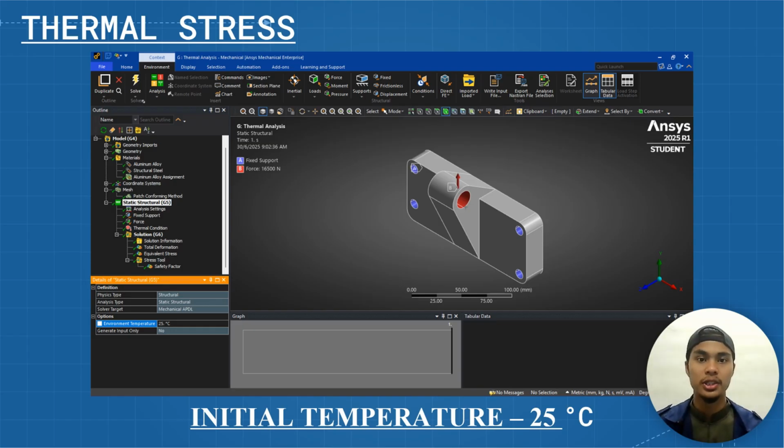Now, we will look at the thermal stress analysis. This is the picture from the ANSYS Workbench, which shows the initial temperature is 25 degrees Celsius. The initial temperature is the starting heat level of a system before thermal stress is applied. It affects how materials expand, contract, and respond to temperature changes. It also has an impact on results, as a higher or lower initial temperature changes stress predictions and system performance. In real-world examples, engineers use it to design safer bridges, electronics, and engines that handle heat better. So, setting the right initial temperature ensures accurate and reliable thermal stress results.